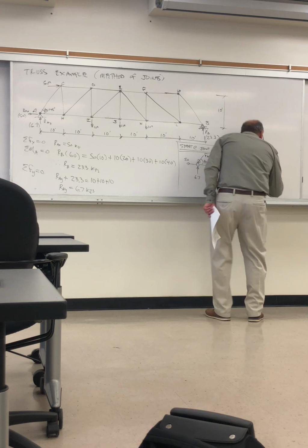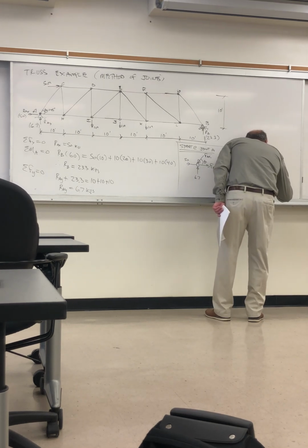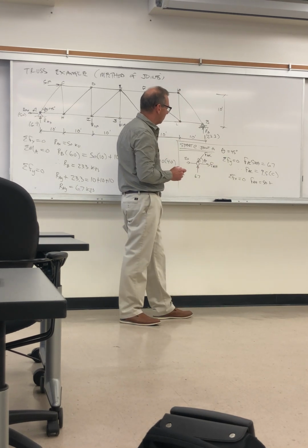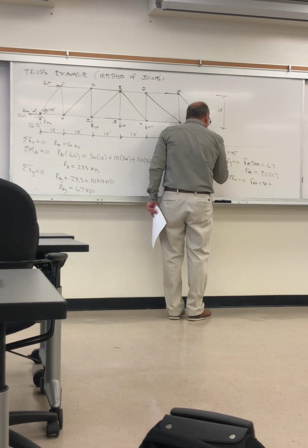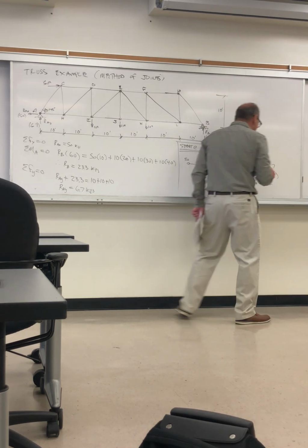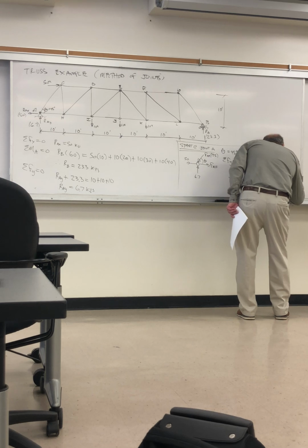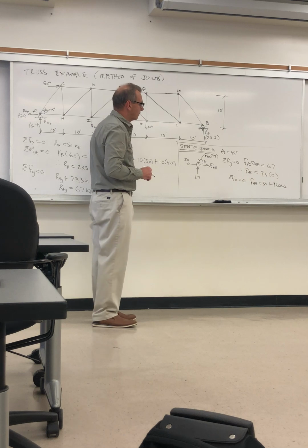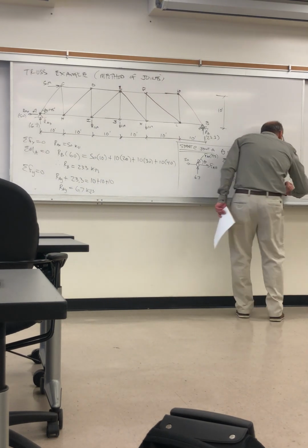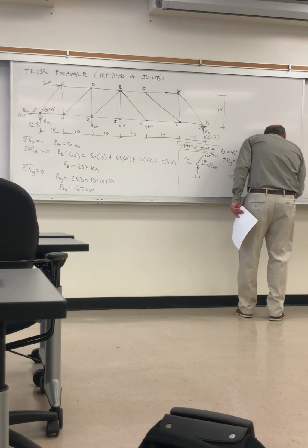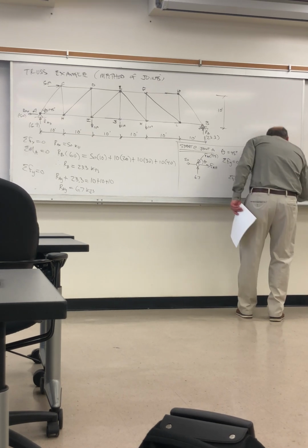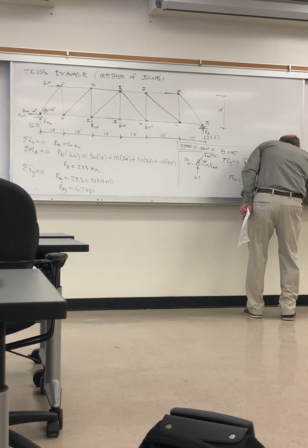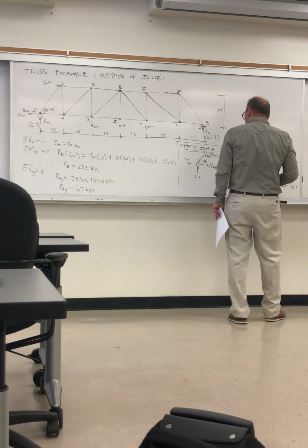So that equals 50 plus the horizontal component of F of AC, and you get that by, so we know this is 9.5 now, so I can just say plus 9.5 multiplied by cosine. Theta is the same, 45 degrees. So you add those together and you get 56.7 kips. And that's tension.